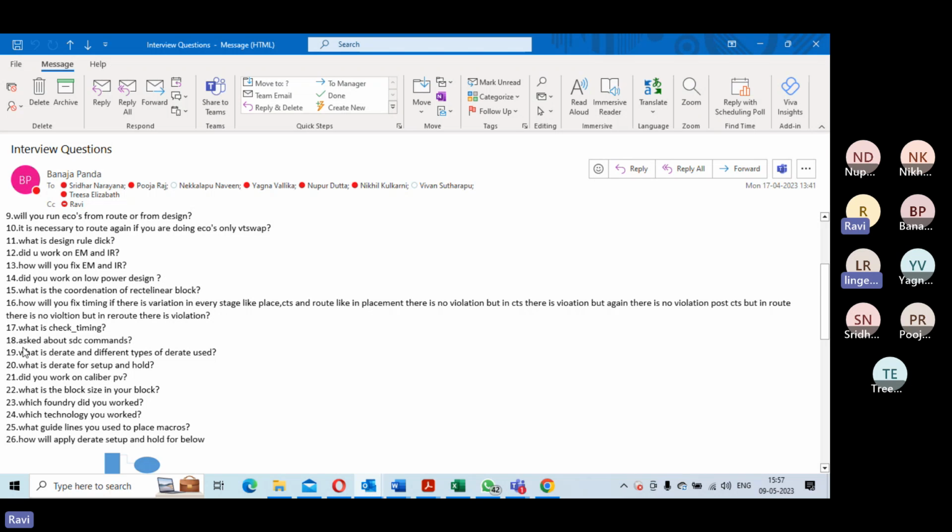If there is more logic in a net, all the cells in the net cannot have the same variation, so as the depth increases, the variation should decrease. That's the statistical model. Similarly, if two cells are located far away, their IR drop won't be the same.